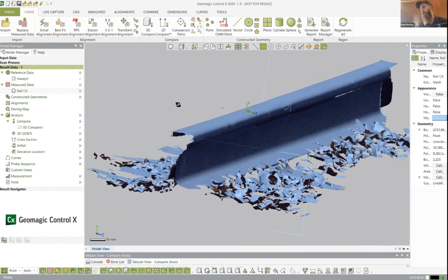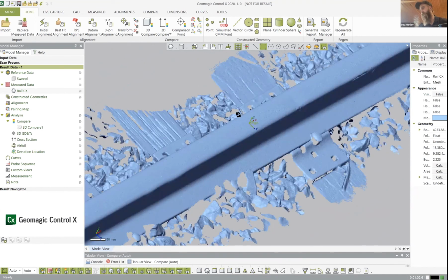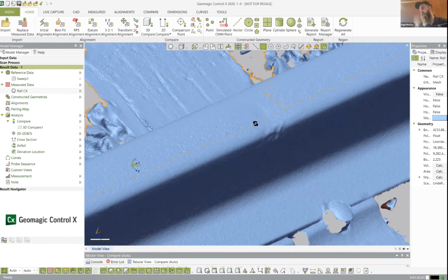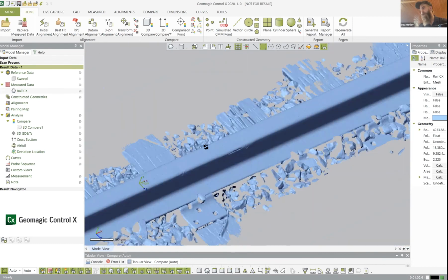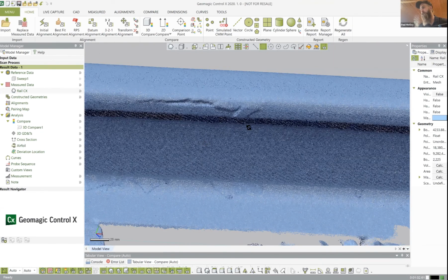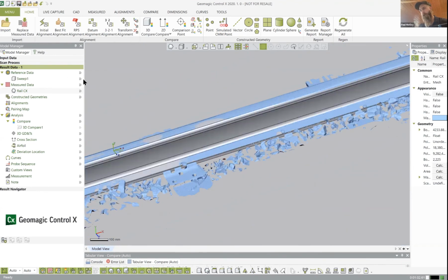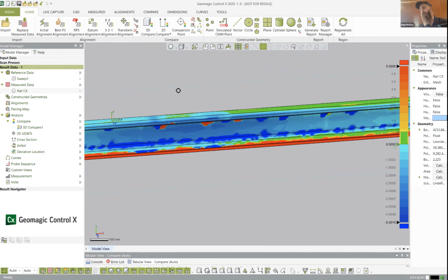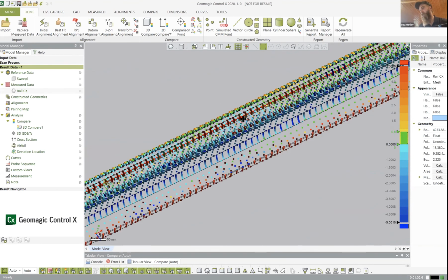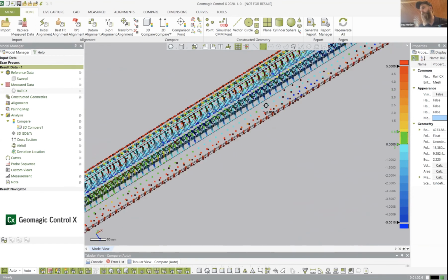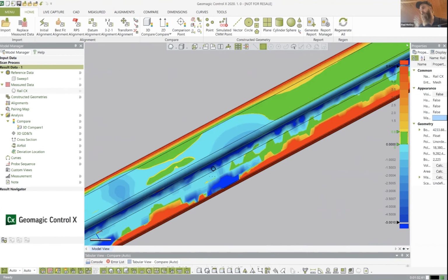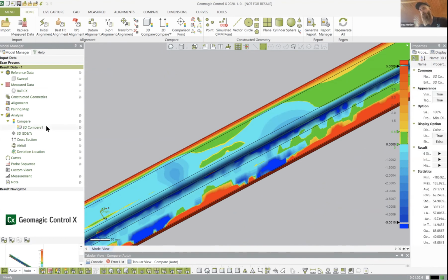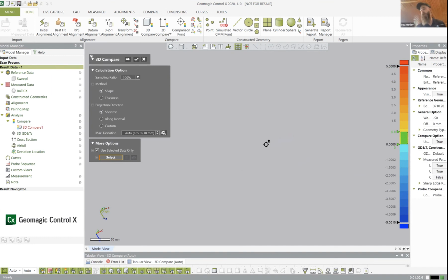Yeah. So we've got our rail section that was scanned again with Leo. And we've got some various distortions. So whether they're engine burn distortions or just some fragmentation that's coming from wear over time, we've got these represented here in our STL mesh. And when we overlay our CAD model on top of that, we can do a real simple 3D comparison that shows how those distorted areas are being displaced on our part and how that's affecting the overall quality of this rail section. So we can see a little bit of an area right here. And we're just using Geomagic Control X right now to kind of show a change of pace. And you can do this inside of Artec Studio as well.